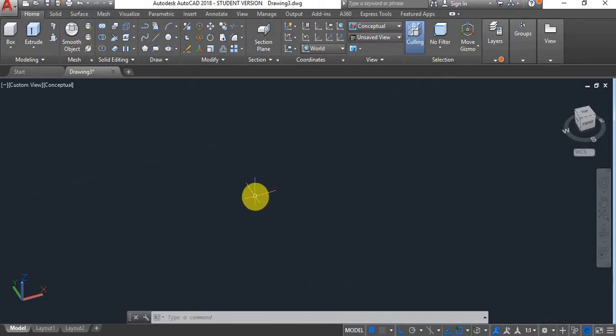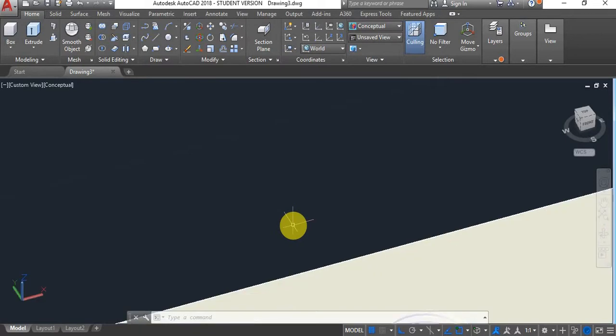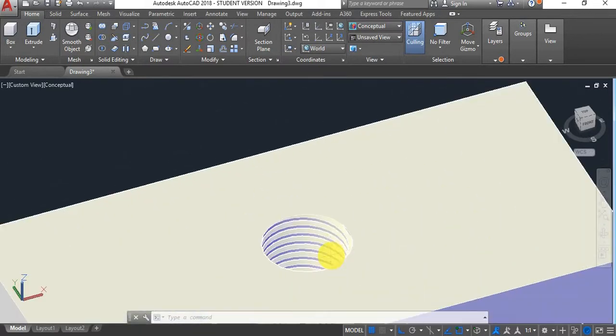So this is completely fine for a 3D model. The only problem is that in reality this simply wouldn't work, because there is no tolerance. So the thread of the bolt would be grinding against the internal thread of the hole, so it wouldn't run through.